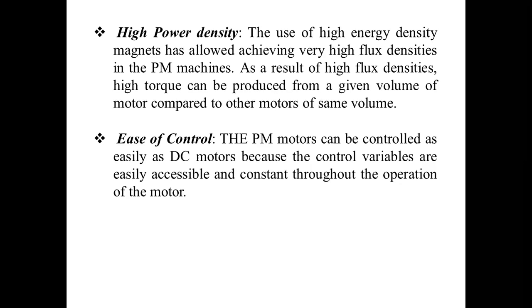We have a doubt also. Whenever permanent magnets are used, the flux value is a constant value. Yes, that is a constant one. There is no other change. If you come across the conventional motors, whenever the field is used, the flux value can be increased with respect to the current, where the current can be changed by using a normal rheostat.